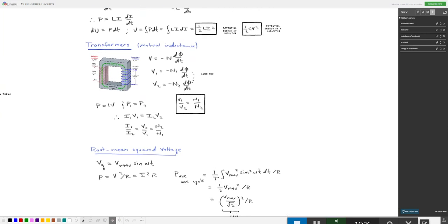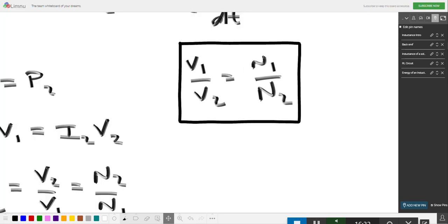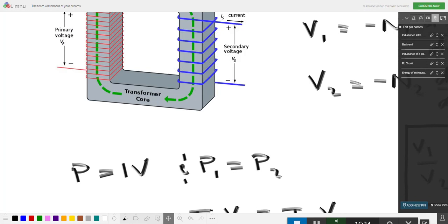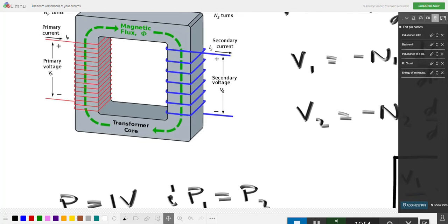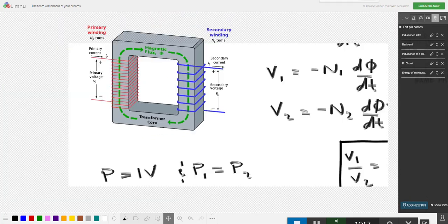All right, the last passive component we're going to talk about is a transformer. And like I mentioned before, a transformer is just this ferrite core with windings on both sides. What makes it work is that the flux created by this is basically a solenoid, right? And the flux created by the solenoid are the same, because whatever flux goes through here travels through this ferrite core and goes through that. So they share a flux in common. So now you have a mutual inductance that's happening. They're coupled. And that allows us to do some neat things.